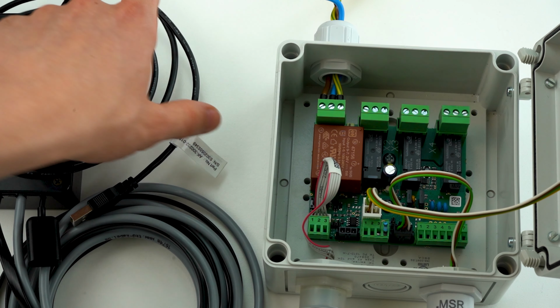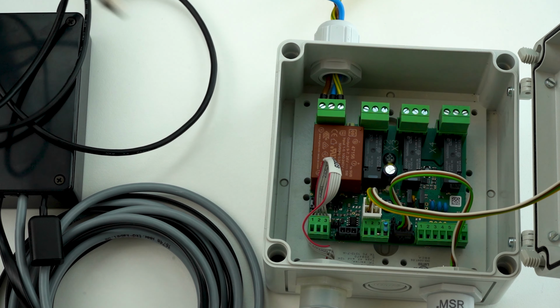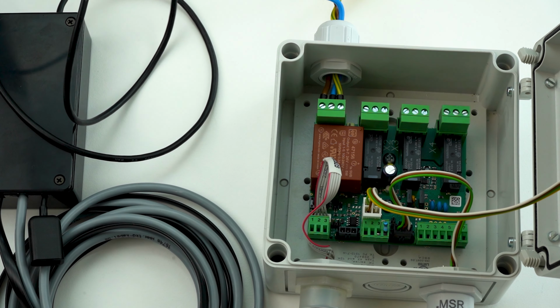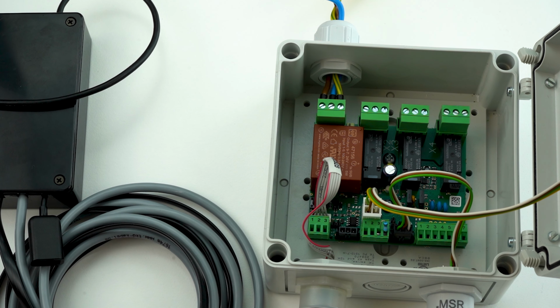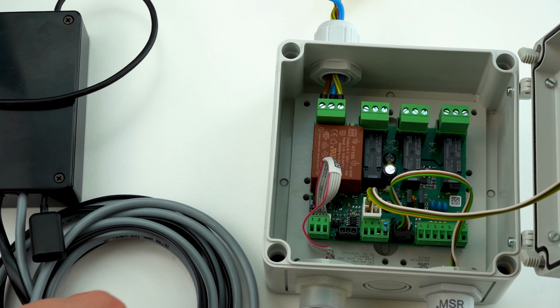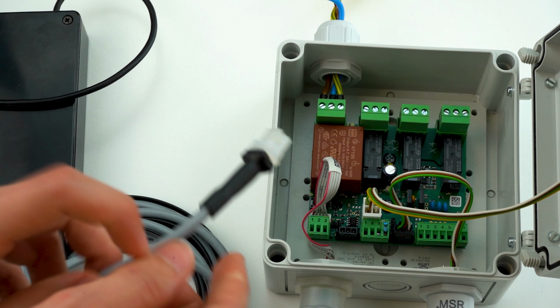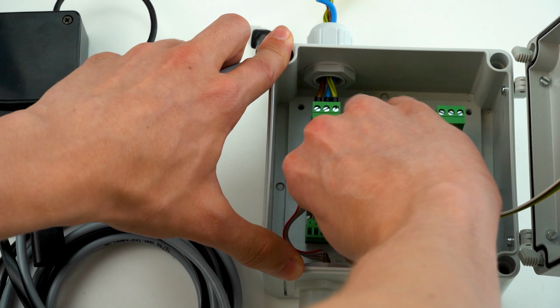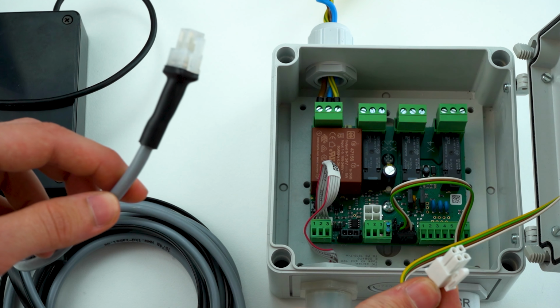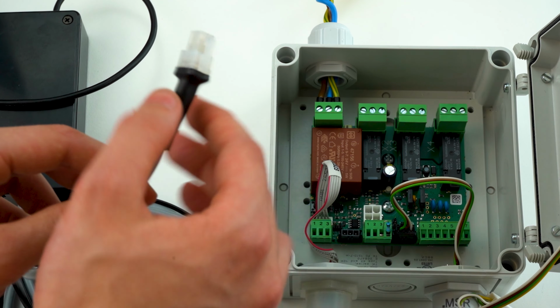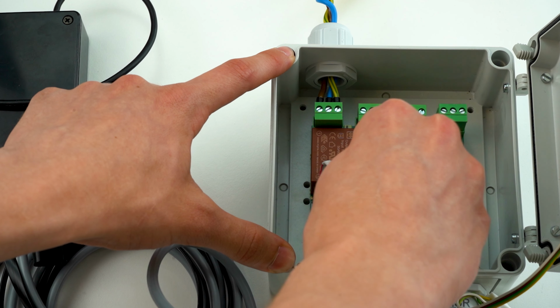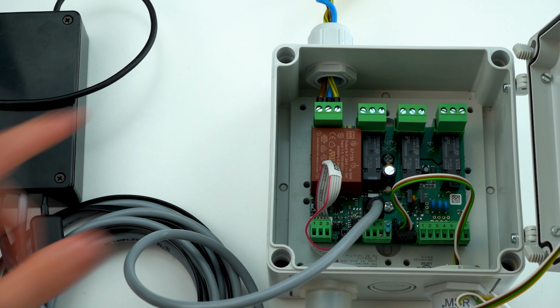You will now need the PCE tool, which has 3 connectors. Connect the USB plug to your laptop and the 4-pin plug to the MSC. If there is a display, it must be disconnected first. Then open the application located in the device internal memory on your PC.